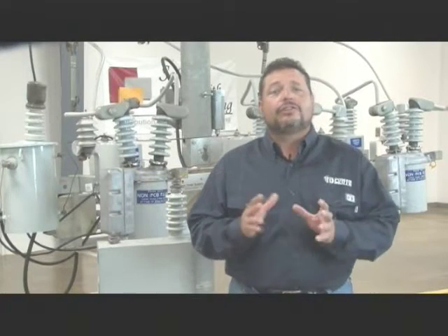The resistors are safety features that are designed to bleed off the charge on the plates. The charge should go to 50 volts or less after the capacitor unit has been electrically isolated for 5 minutes. While this is designed to reduce the shock hazard to personnel working around capacitors, you should always assume that a capacitor bank is fully charged until it is grounded or shorted.